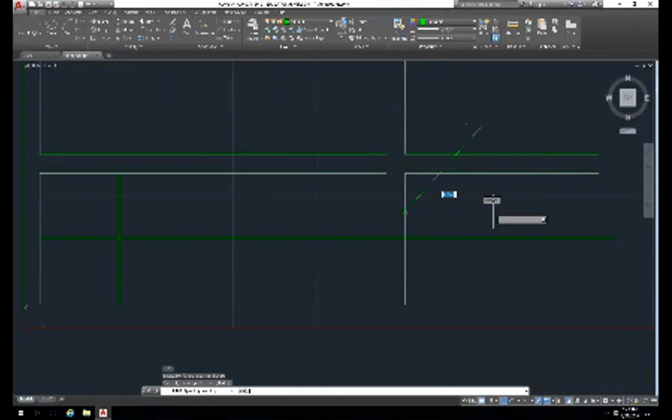So now we can draw. Press enter to finish this command. So now we can draw another line. We can mirror this one. MI gets us into the mirror command. So we select objects, now press enter, saying that we finish selecting objects. I'm going to use a shortcut for middle point, MID. I'm going to select the middle point on this line and go down. I have orthogonal mode locked in, and then press enter to finish drawing. So now if we do trim and we select this line as the trim line and then enter, now we can select objects to trim off and then press enter to finish the command so that we're not in the command.